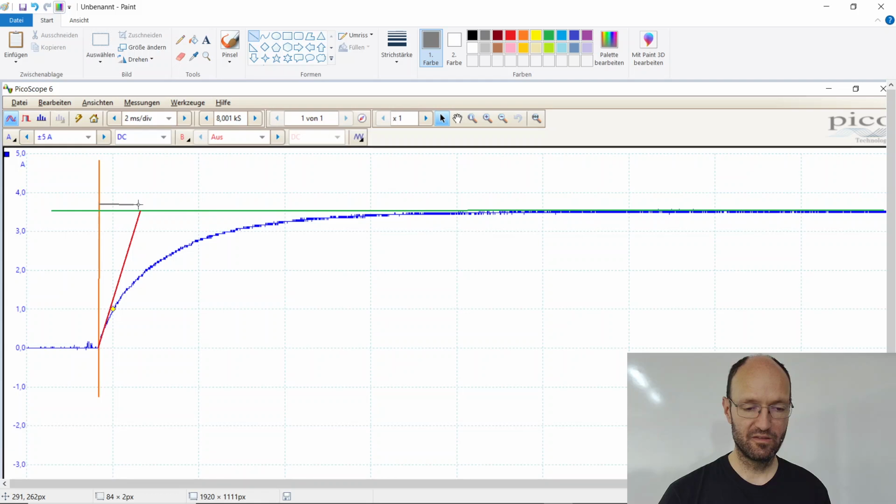And so if we take a bit less than 1 millisecond and multiply it with this rotor or motor resistance that is a bit more than 1 ohm, then we get approximately 1 millihenry. I'm sorry, I'm always confusing the milli and the micro there. Yeah, and that's why we get this nice fit. But we can check: the time constant is the inductance divided by the resistance. If we take more inductance,